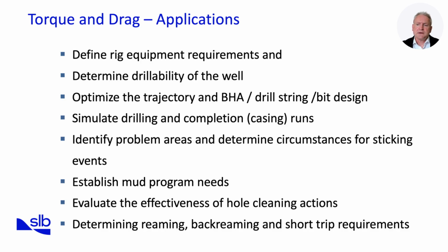Fourth, we can simulate drilling and completion runs, including casing running, to verify that casing can be successfully deployed to bottom. Fifth, torque and drag help us identify problem areas and circumstances for sticking events by highlighting sections with high side forces, tight doglegs, or poor cleaning potential.